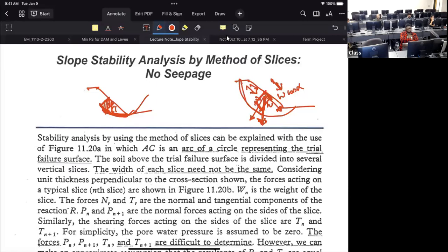Your load has to be mobilized. So when the soil started moving, it tried to mobilize it in a pattern. The easiest way to mobilize it is creating a slip surface. That's why you see the slip surface. That's how you create the instability.